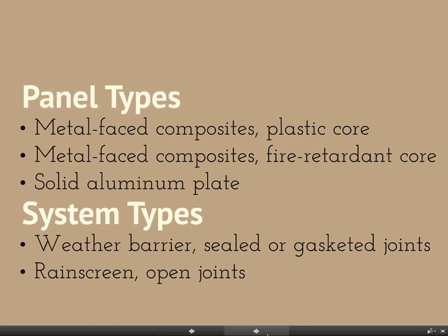So my silver metallic job had ACM panels and a, shall we say, a crazy problem with an expansion joint, a seismic joint that had a big old door, because they really wanted to hide it. So our sheet metal fabricator fabricated a door for the expansion joint, and of course it looked beautiful. It was beautifully fabricated, but it was spray coated instead of coil coated, and there was no way he was going to be able to match the coil coated ACM. And because we didn't order him ACM to make the door out of, there wasn't anything that could be done.